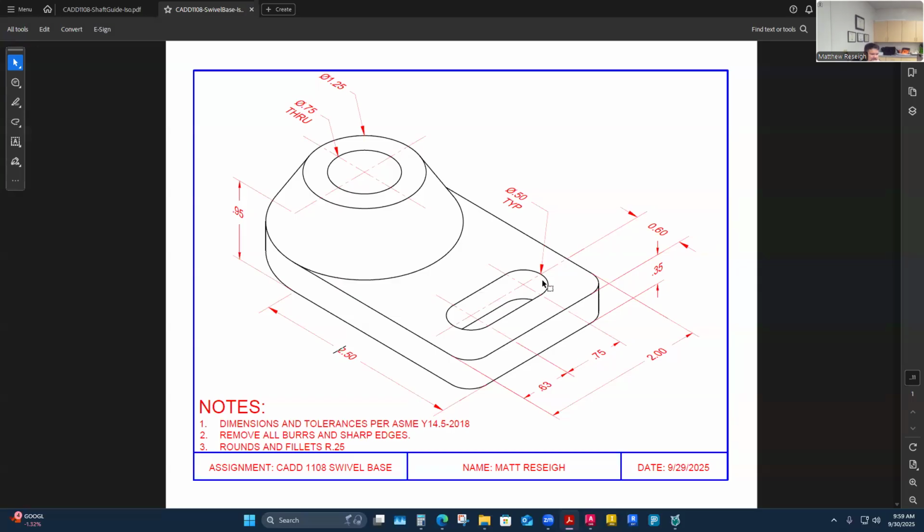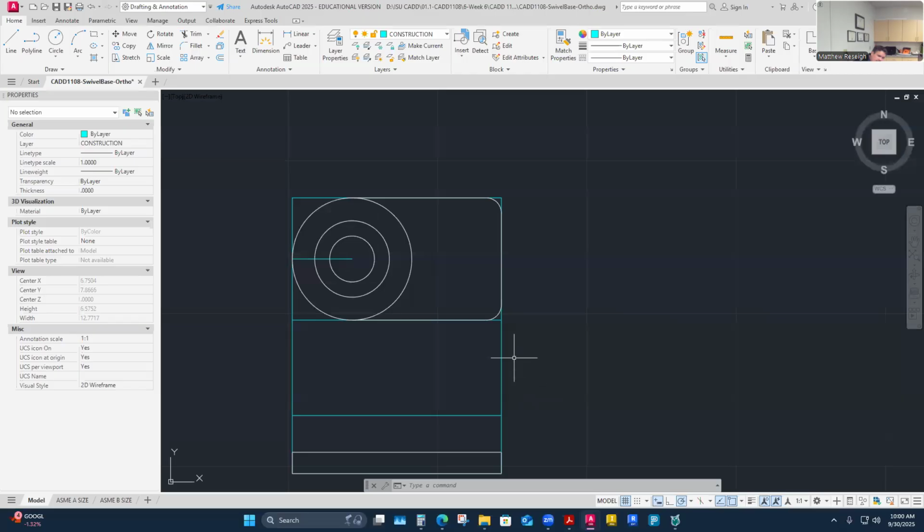It's over 0.6, and it's 6.3 to the first one, and then 7.5 to the second one. So I feel like I'm going to do 2 circles here, and then 2 tangent lines to make my slot. Pretty common. So I might just need to know a line that's like 0.63 out and 0.6, and then a line from there that's 0.75 and 0.6 out. So I could just do one line across at 0.6. So maybe I'll do that as my first construction line.